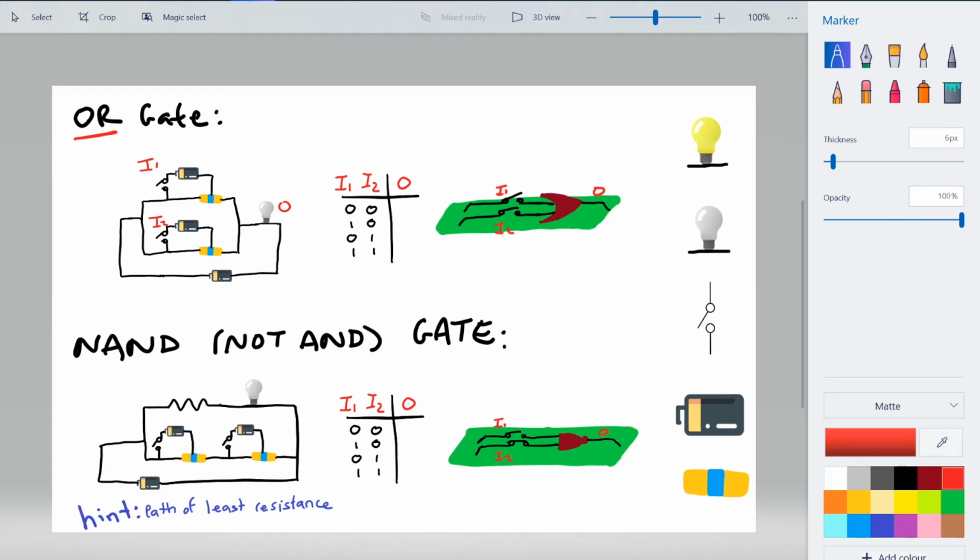So checking out the first situation right now with both input bits off, so the switch is open, we see that electricity coming out of the bottom battery reaches the junction and then can go through either the transistor from input 1 or the transistor from input 2. However, since both inputs 1 and 2 are off, then they stop there, and so the output bit is off.